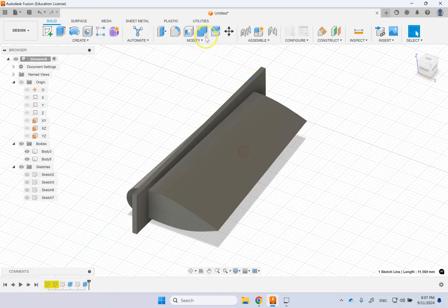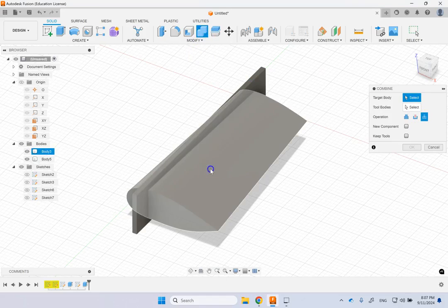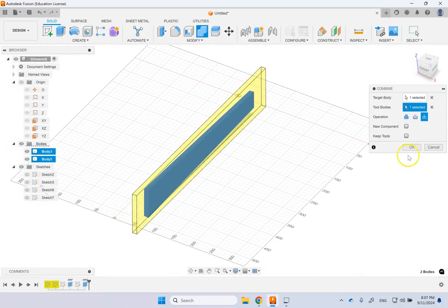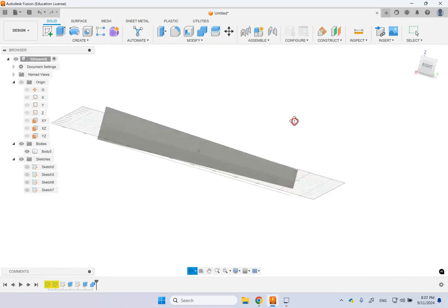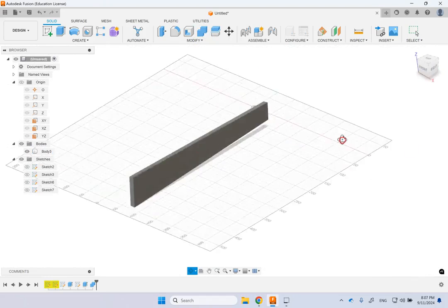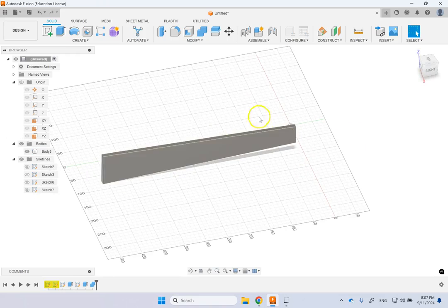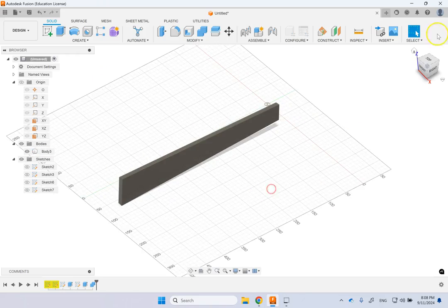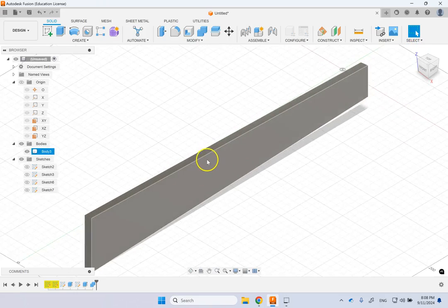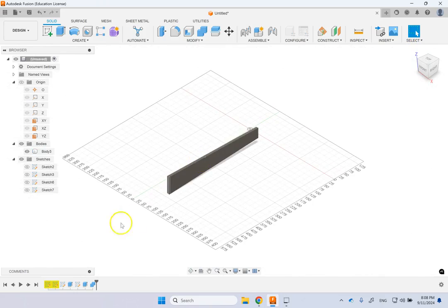And now I click here, intersection, pick this one, and now you can see that you clearly have a taper angle as well as the cross section, which is not a rectangle. So you can get the spar. Or if you made the plate go basically sideways, then you get the ribs. So here is an example of logical operators in internal structures for the wing.